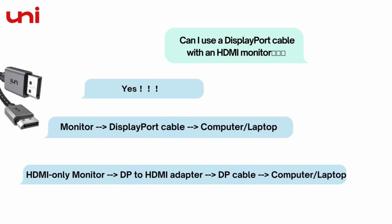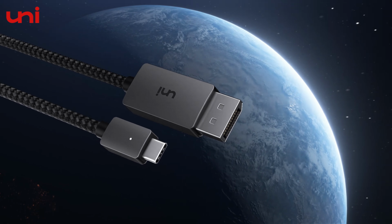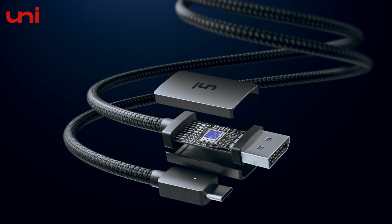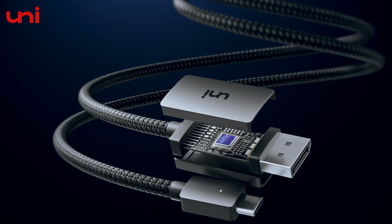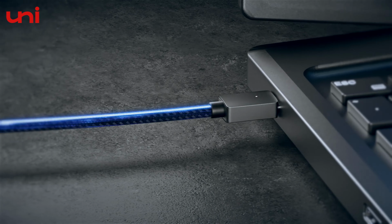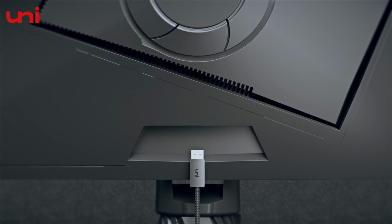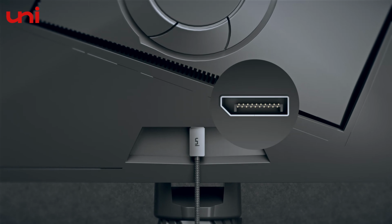Ready for an upgrade? Switch from an HDMI 2.0 cable to a DisplayPort 1.2 cable for better capabilities. With higher bandwidth, DisplayPort 1.2 supports higher resolutions and refresh rates compared to HDMI 2.0. Plus, it has the added bonus of supporting multi-stream transport, MST, for splitting a single DP port into multiple displays.